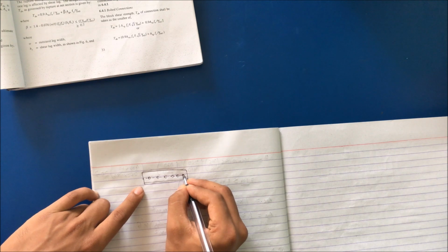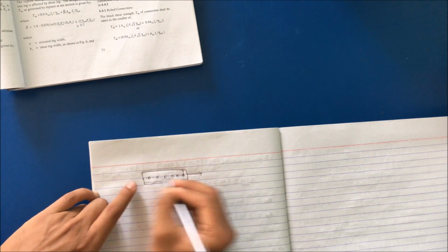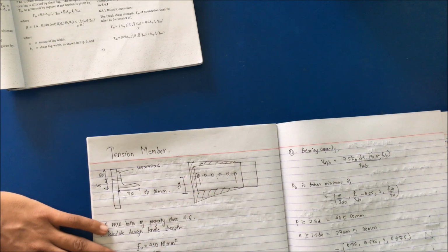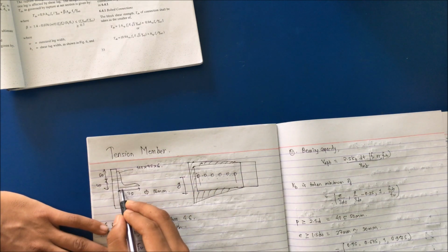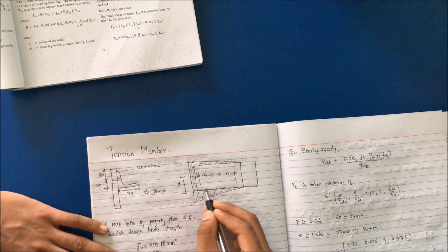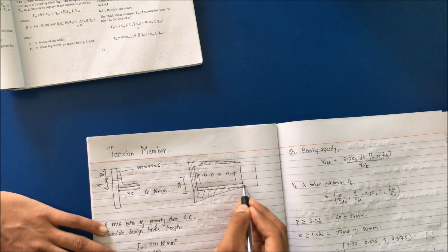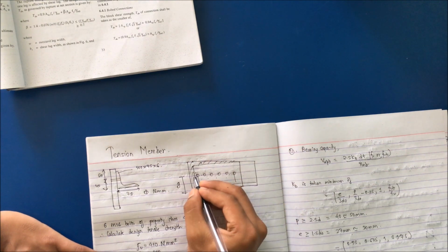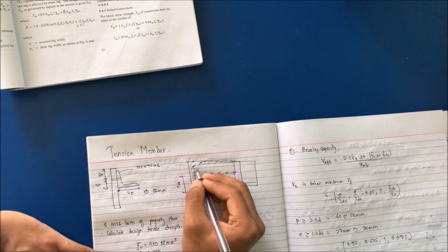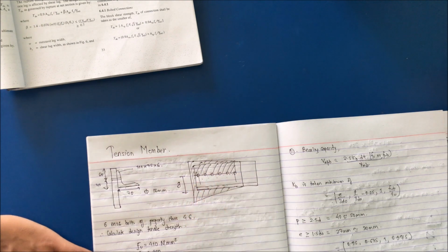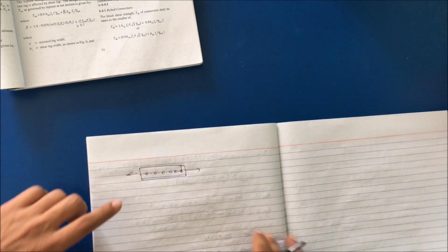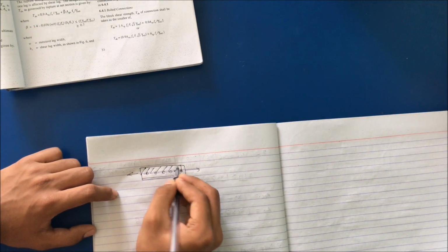Now for tensile failure, it has to go perpendicular to the direction of load applied. So if you see in our figure, this is this projection of this, so this line is here, and this line will be acting in this way. So the failure does not occur in the downward direction, rather it fails in the upward direction, and this will be our block shear. So this is our block shear.